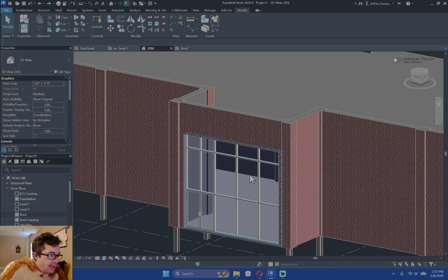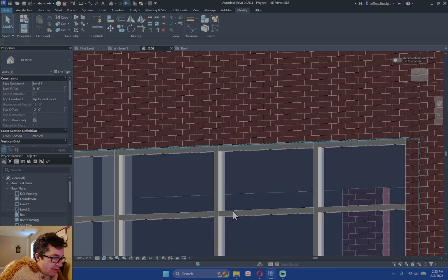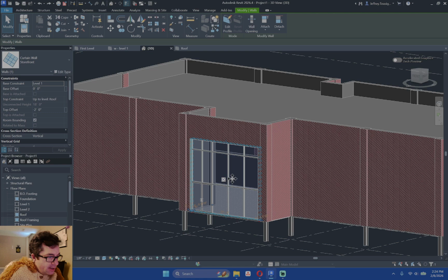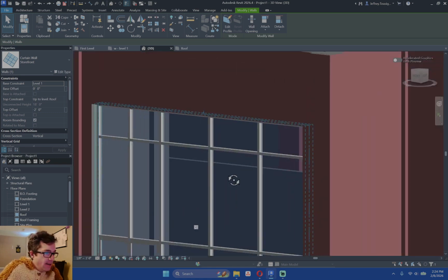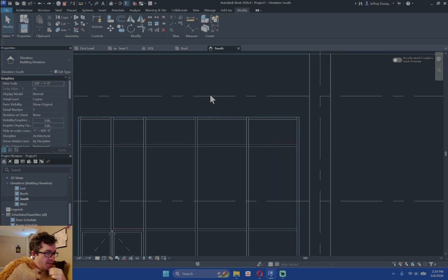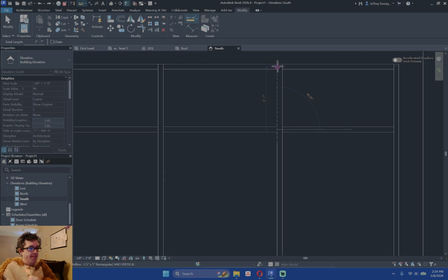And the way that I'll do that is I'm actually just going to tell all the mullions on this curtain wall system to go up whatever height they need to in order for these to go where these are. And then that will make the bottom go up. If that doesn't make sense out loud, it'll make sense when I demonstrate it. So, how far up would I need to adjust those? So if I take these and I move them up 2'7"